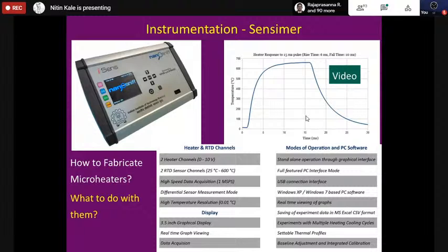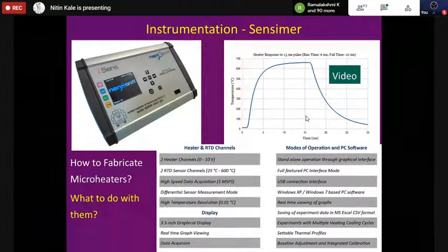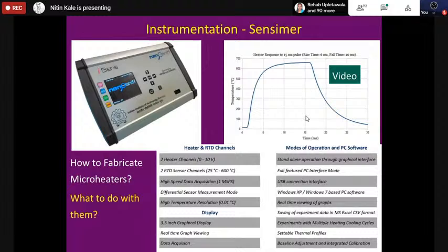Now you can have a calibration situation. You put 1, 2, 3, 4, 5 grains of salt, and you find how much is the change in rise time. So that could be a very interesting experiment for PG students, or maybe even some higher level BTech students at your labs, for sensors, instrumentation, MEMS, etc. These are good kits to play with.